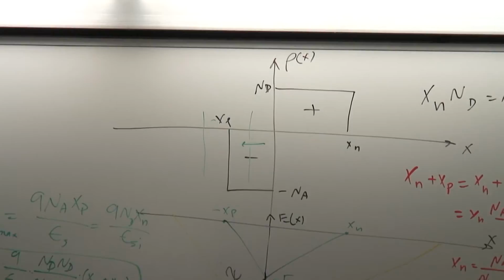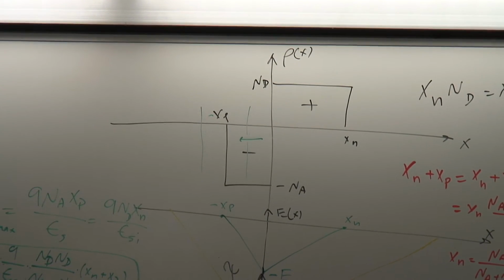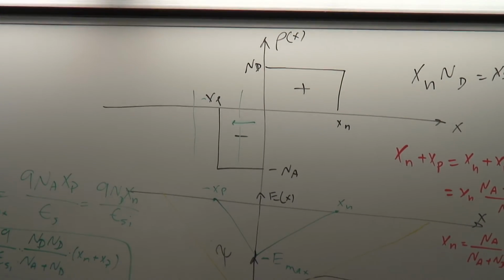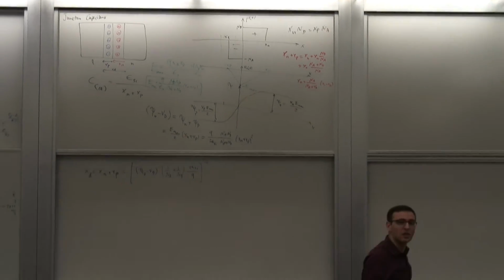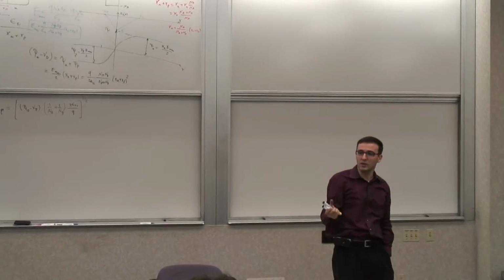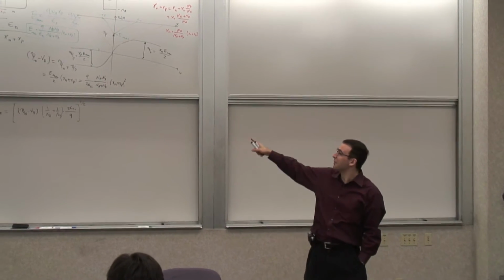Sum of the charges to be 0, that has to compensate the charge on the other side. So it has to extend over a large distance. Right? So it's interesting. It's the lightly doped side that determines the width of the depletion region and hence the capacitance.